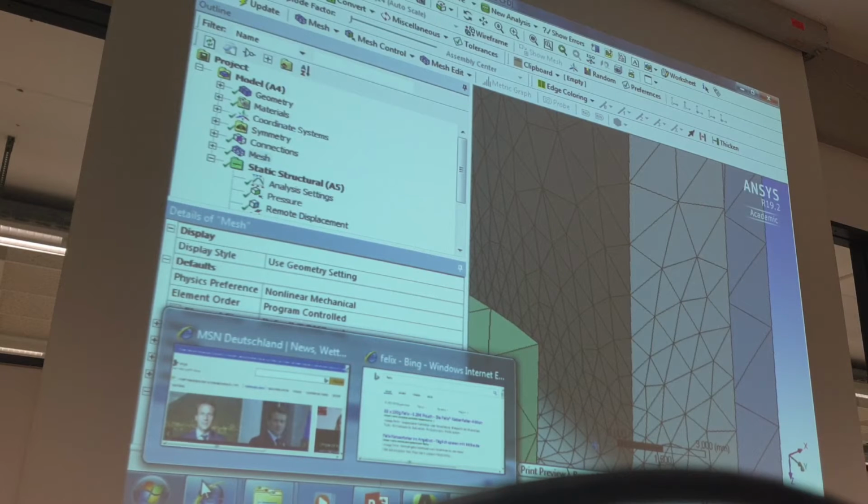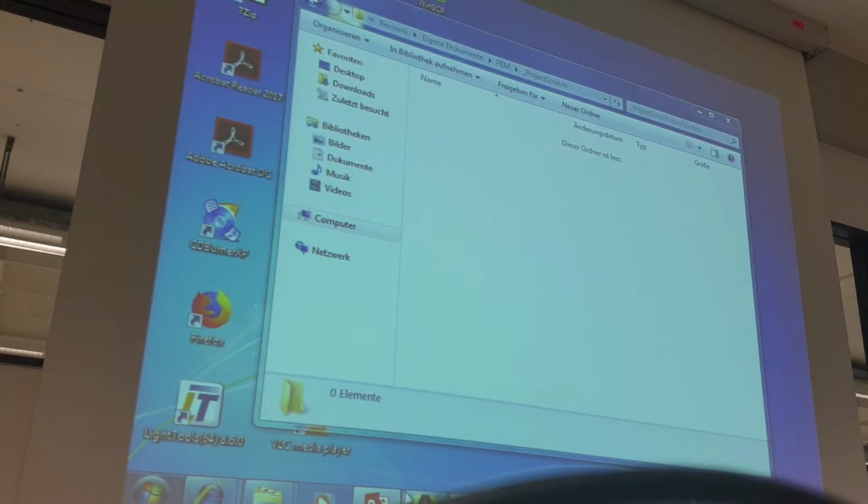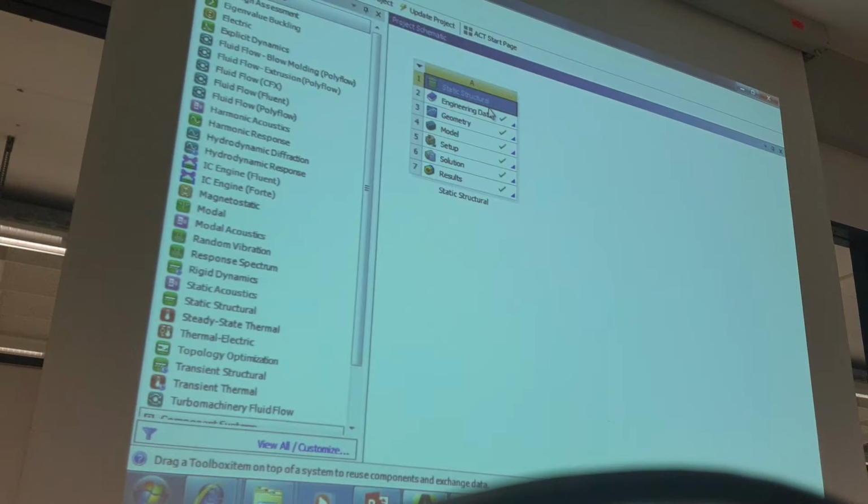Yes, and up to about 500 is direct better. Yeah, nobody knows how much. Yes, for every task it is different. But normally, if my nodes are, for example, fewer than 100, 200 nodes, then direct is quick. And we want to check it first. How can I use my theoretical knowledge now in ANSYS? We can use everything. ANSYS allows everything. I can duplicate, and now I will tell the program, okay, now I want to calculate this with the direct method. Yes, it's not better. Direct is more exact, yes, like exact. That's the wrong word. It's the same result.